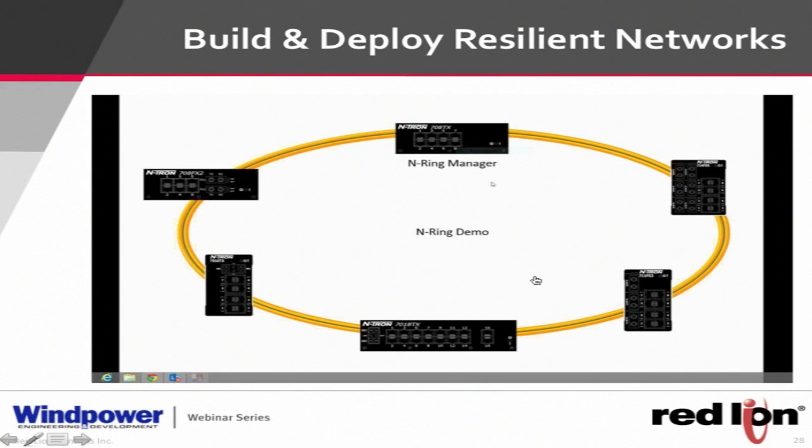the way that they should, which means plugging them in the right ports, port 1 and port 2, which carry the ring. It's either the first 2 ports or the last 2 ports, and then log into one of the switches and make the change from auto member to master. You don't have to log into every switch. You only have to log into one.